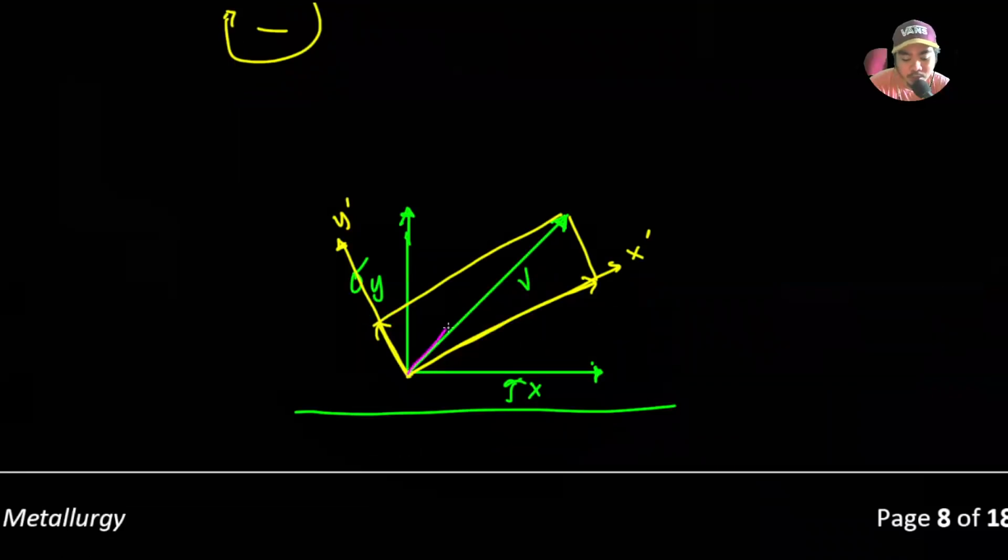So, if I do an axis that is something like this, kunwari, i-rotate ko yung axis ko, and this is my y prime prime axis, tapos nandito yung x prime prime axis ko. Then what I actually have is 0 yung tau ko. So my tau here, for this type of orientation, equals 0, and meron lang akong isang value, sigma y, which is equal to kung ano yung vector mismo. Tama? Which is very convenient sa akin kasi hindi ko na-breakdown eh. Isa lang yung value ko, wala akong shear stresses, puro normal lang. This is what we actually call as sigma p. This is our principal stress.